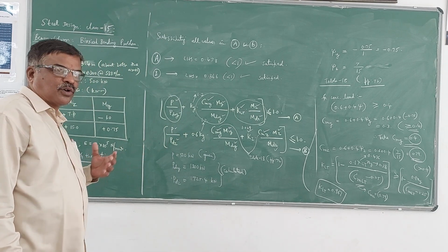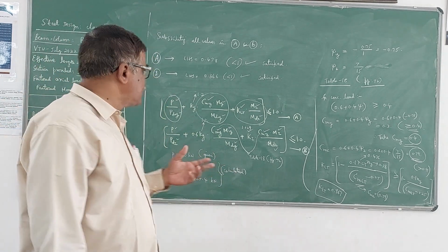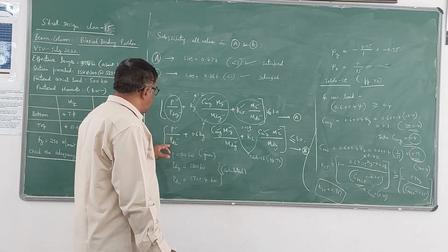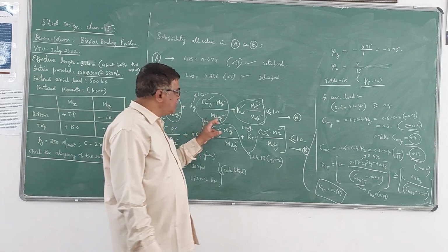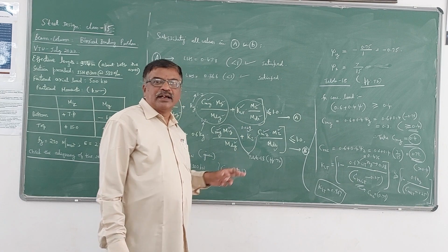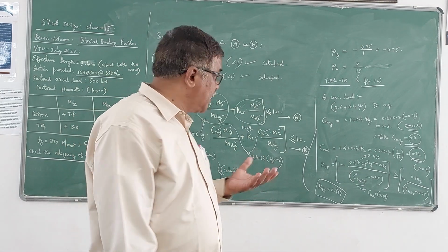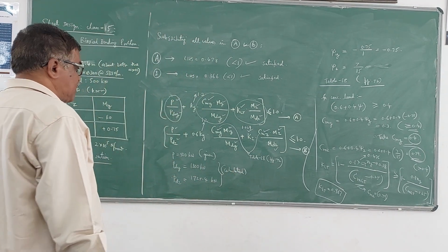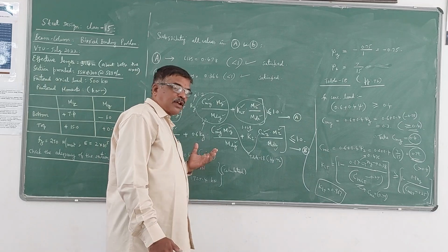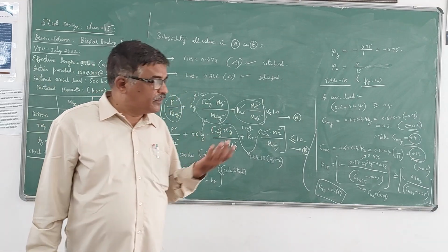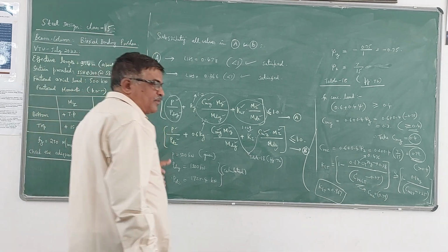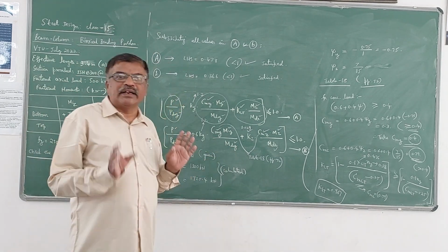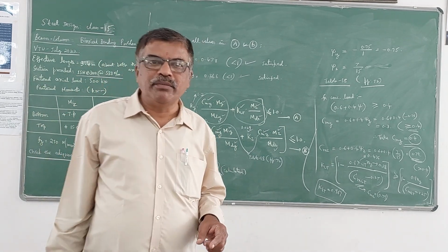But for that also, we require certain values, because these PDY, PDZ values you can get from the check for compression. These MDY, MDZ values you can get from the check for bending. And of course, the third one is that the MCR value we have to compute. Then you have to calculate the MDZ value, and this is the fourth check. So if you do all the 4 checks, then that is the complete design of a beam column.